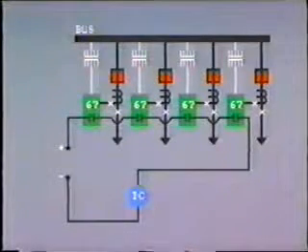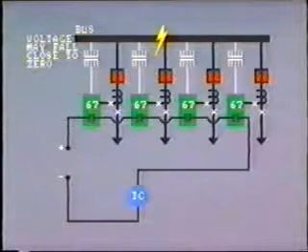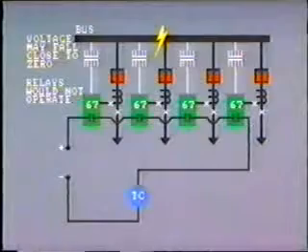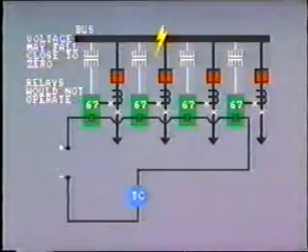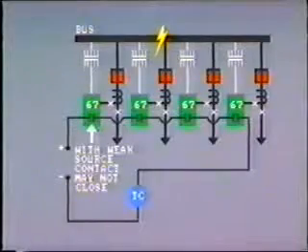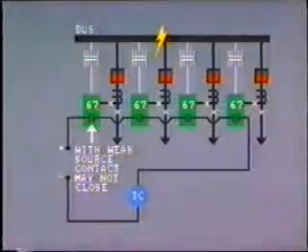If this is taken from a voltage transformer or the bus, the voltage may well fall close to zero during a bus fault, and therefore the directional relays would not operate. Another problem can result from weak sources, or sources that become weak during certain switching sequences.